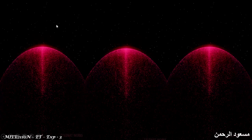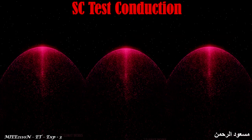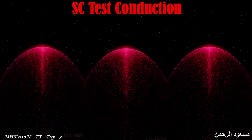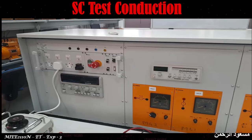So now we are going to see about the short circuit test conduction. How to do the short circuit test. The connections are given as per the circuit diagram, and now you have to remember what you have done for doing the open circuit test. We have supplied the rated voltage in the primary side of the transformer for the OC test, the open circuit test.